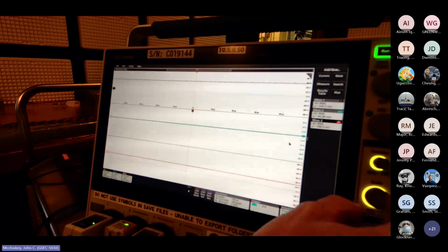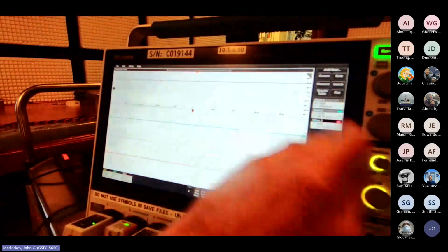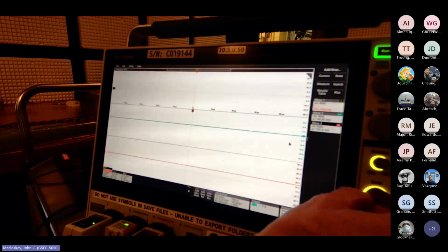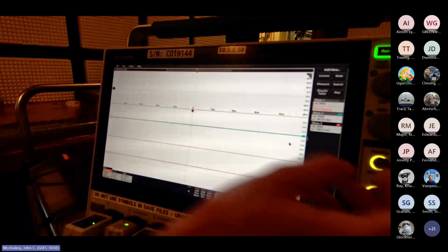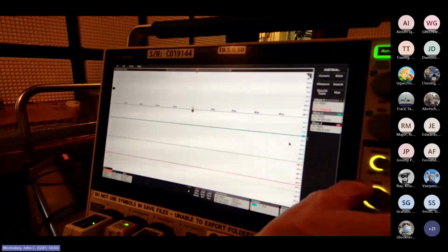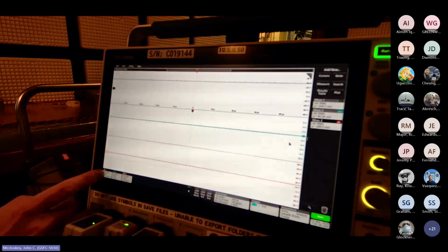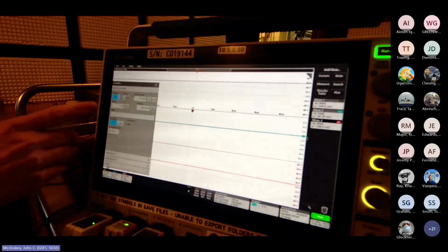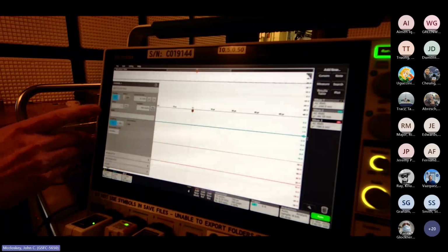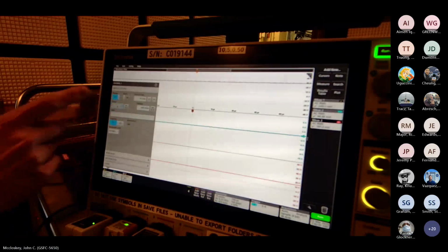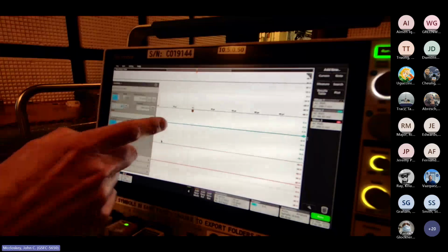So when you want to try to get more resolution as to what's happening there, well, okay, you expand the vertical scale. Well, you lose the signal because it's expanding the DC component as well. But the more effective way to do that is to set an offset. So however your scope does it, hold on.